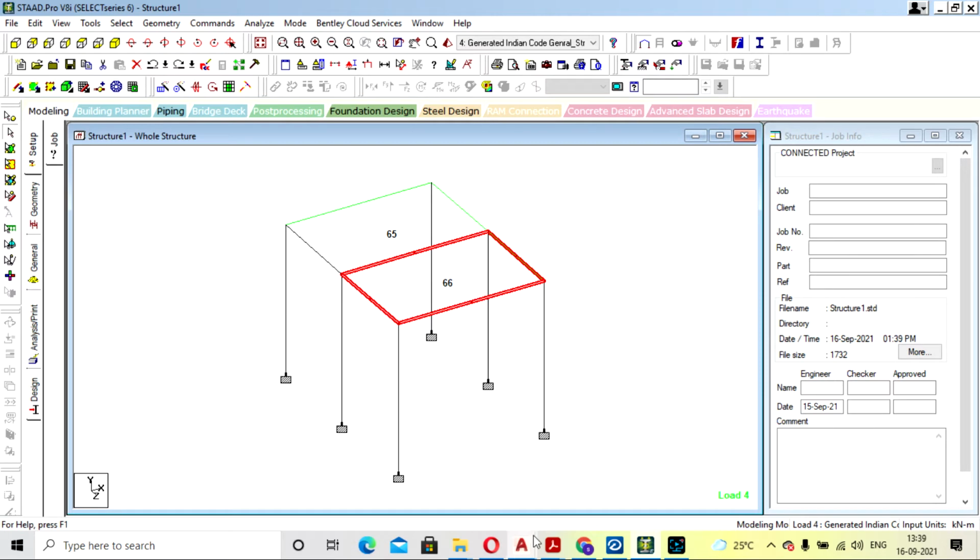If you only want to get the area of steel, then you will go for direct and not do meshing. If there is a long, tall or high structure where you want to provide different floor live load or concentrated load in different areas, then you can do the meshing, so that it will be divided into parts. Otherwise it only creates from the center. If maximum load is coming here, the software does not detect that in normal values, but it will if you create meshing.